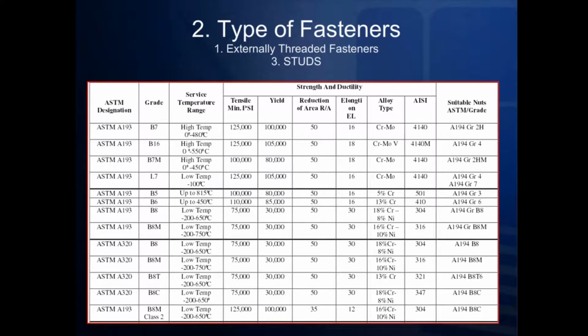As you will notice, each grade is designated for different applications as they have different tensile strengths and service temperature ranges. It is also important to notice that many charts like this will also tell you what grades of nuts are acceptable to mate with the corresponding studs.